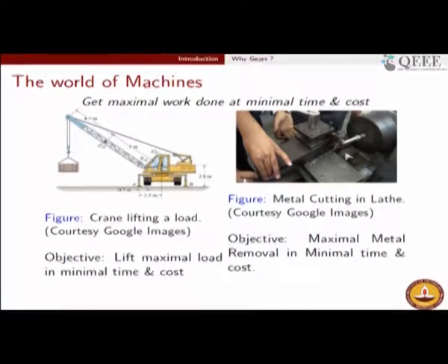The load will increase and the driving torque given by the motor which runs this rotating spindle is limited. The maximum driving torque is limited. So, at some point you will not be able to take a depth of cut greater than what can be delivered by the motor.